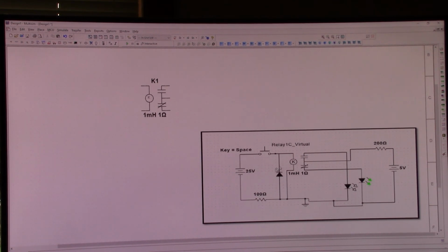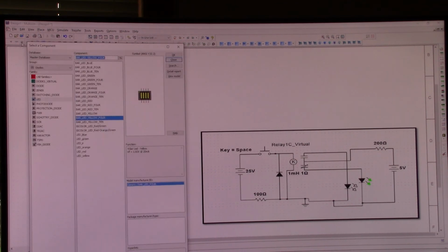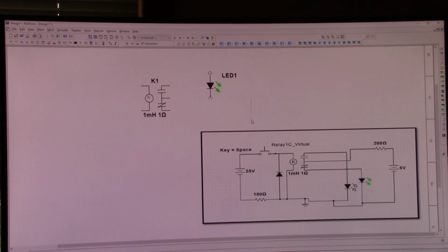You see how this device is an arrow looking thing, like I said. So if you go to the top left hand corner, design, file, and then it says source, basic diode, and if you go down to LEDs, it's right there. And I need a green LED and I need a red LED. Okay.